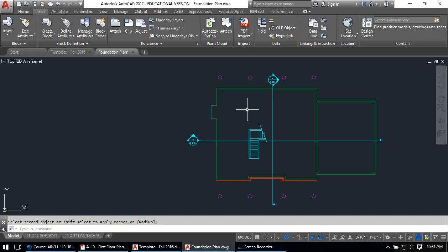The same with windows, especially when you're beginning window design. You might not know the manufacturer you're using. In fact, as it goes out, you might not know the manufacturer. And there's slight differences between windows and window brands and what's the prices and options and all these things. And so if you dimension to the center, it will be placed in the right spot, and you have some sort of give and take along the edges.